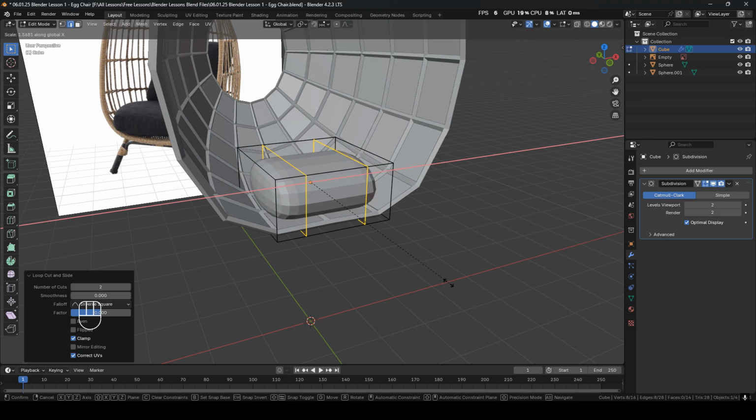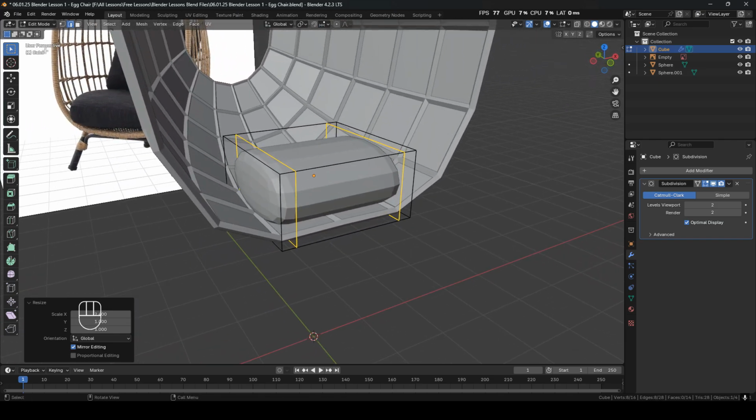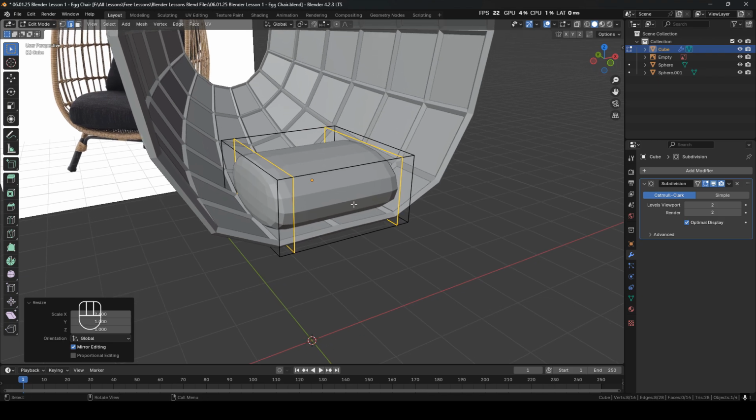So we've got these edge loops. We're going to push them along the sides. I'm going to say we're going to push that, I'd say 2.4. Let's have a look. Yeah, that'll do for now, just 2.4. I do like to use measurements and not do it freehand by eye, just in case I've messed something up, you can always come back and redo it. And you can guess roughly where it was before, because it's a nice round number.